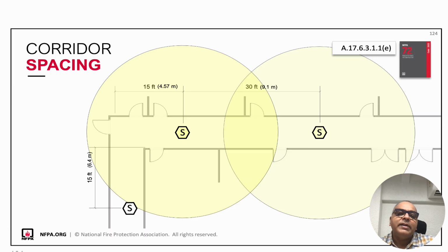Detectors near doorways. Door leakage and ventilation increases early smoke entry into the corridor. Early warning improves due to natural channeling of the smoke. In narrow corridors, smoke is funneled along the ceiling. NFPA allows increased detector spacing because we can predict smoke travel more reliably.